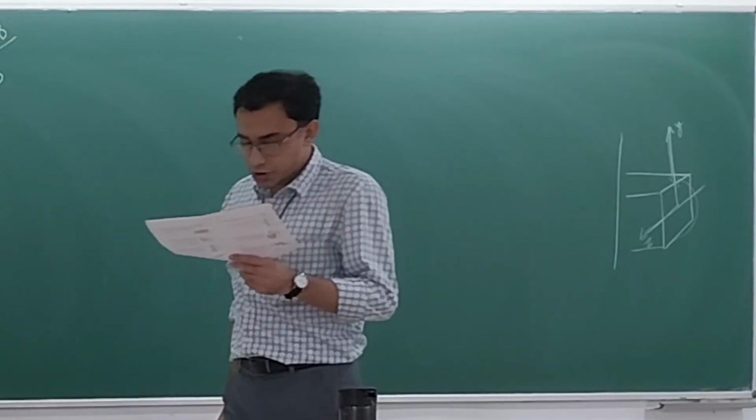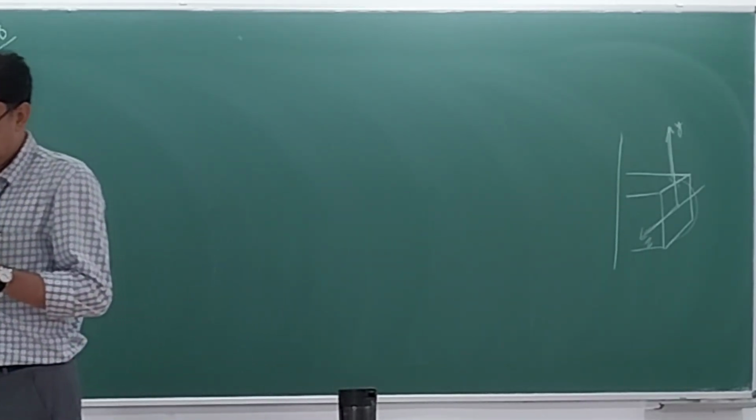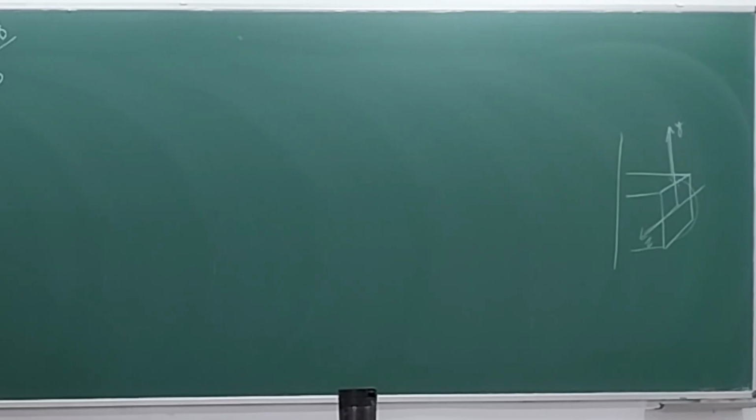The cylindrical portion of the compressed air tank shown is fabricated of 8 millimeter thick plate welded along a helix forming an angle beta equal to 30 degrees with the horizontal. Knowing that the allowable stress normal to the weld is 75 megapascals, determine the largest gauge pressure that can be used in the tank.